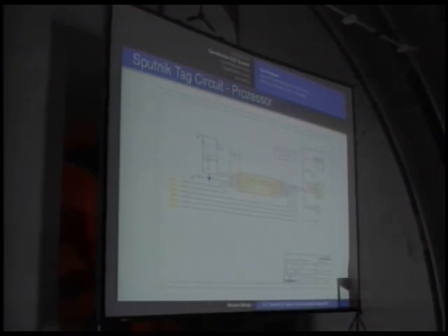Oh, that's also an interesting part. There is also a new change in the tag design. You can choose between two operating modes. For the current use, you obviously want to constantly power the tag, because it automatically sends data out. But if you move the 0 ohm resistors, there is a mode A1 and a mode B1. If you only connect this resistor, then you can turn on the tag with a push button.